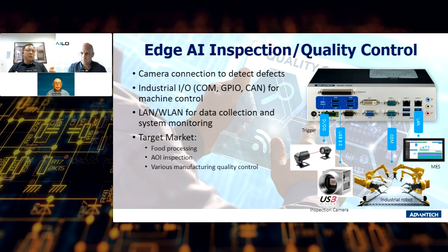And then control, say, for example, gates to open. Like very often you see, particularly in agricultural food processing applications, different sizes of eggs, different sizes of fish. How do you sort them? Those are usually controlled by camera and also the GPIO together at the same time to control the mechanism to send them to different sorting locations. Ethernet, or wireless Ethernet, basically some form of communication.